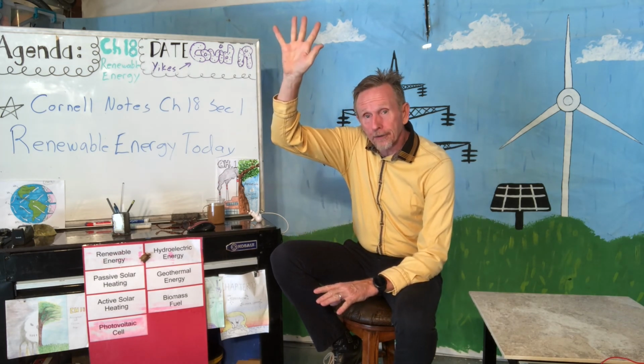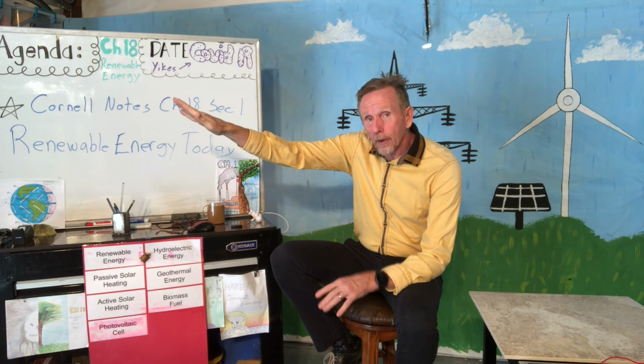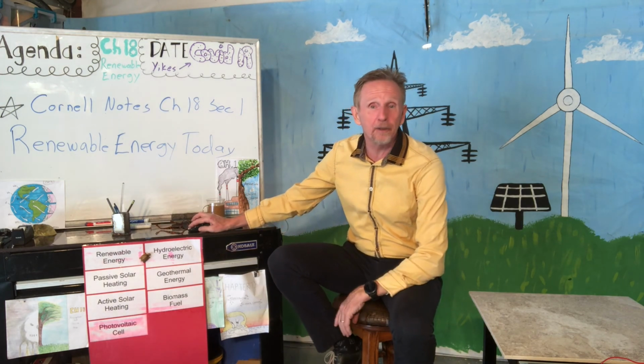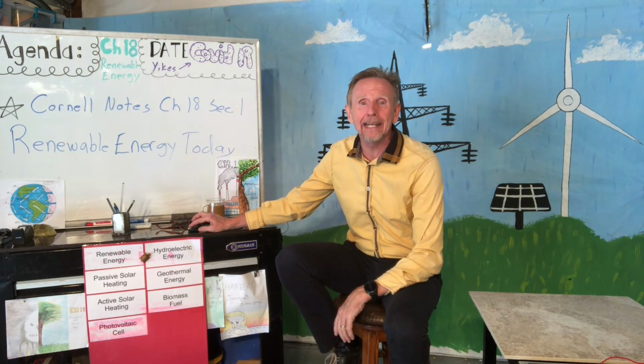The eaves come over and that blocks the real direct sunlight in summertime when the sun's high, but when the sun's low, it misses the eaves and hits those nice big bay windows of mine and lights everything up, giving us some free heat. So some of our houses are positioned and designed specifically to take advantage of it, and others not so much. It just depends on where your house is, how it's placed, etc. But anyway, that's passive solar heating.